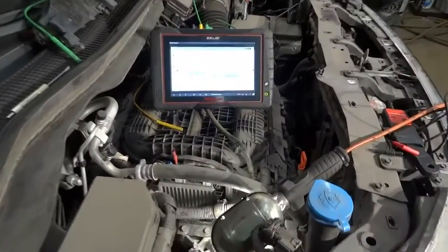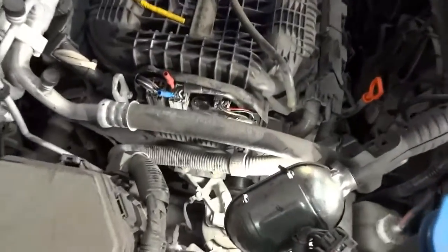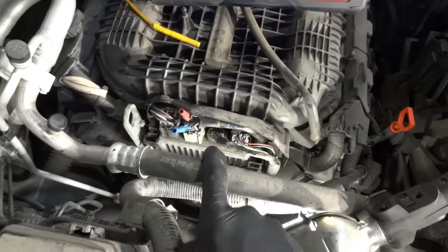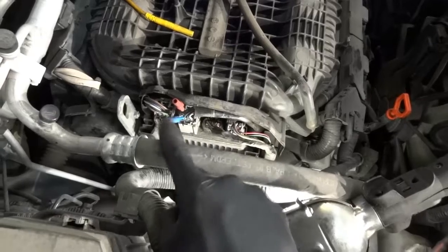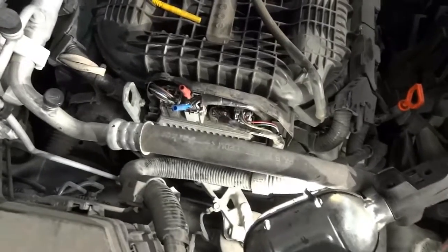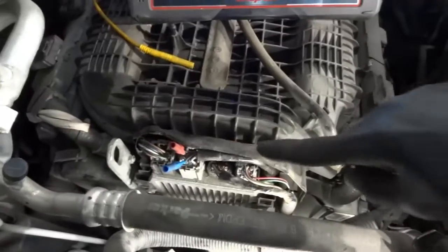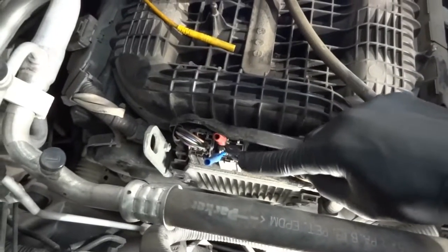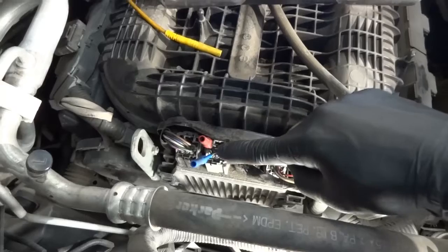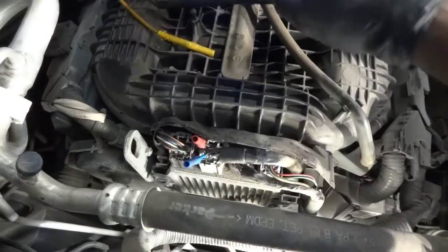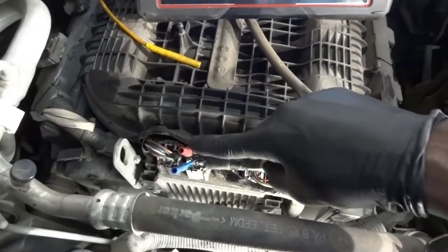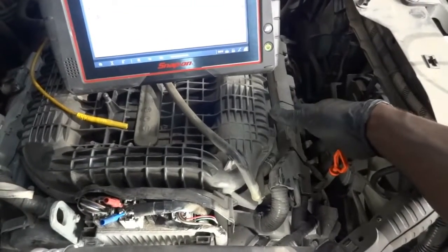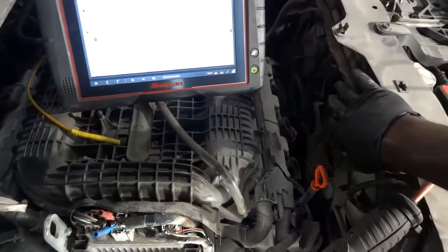Alright guys, so I got all the engine covers removed, and right over here is the injector control module. So this module controls the fuel injectors and the fuel pump. So I got the cover of the injector control module removed. Right now I'm back probing 2 wires for injector number 4. Okay, so I'm back probing the wires that go to cylinder number 4 on the second bank, so the bank in front of the car.